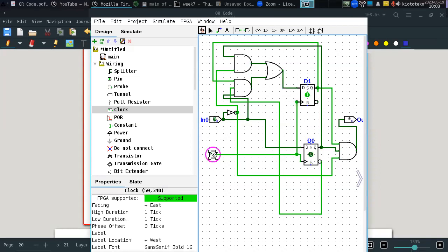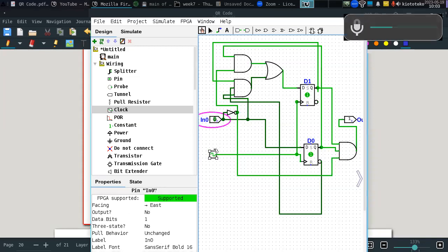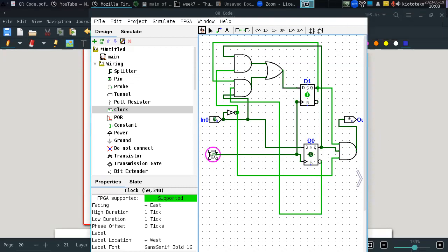Well, you see that it's detecting it, but I don't know what's happening with the clock. Maybe I'm not doing it correctly, but you can see that at some point we have a 1 there, which is because we have 1 0 1 0. But what happens if we just maintain the 0 there? Well, now you don't get a 1. So yeah, this circuit works. So this is sequential logic for you.